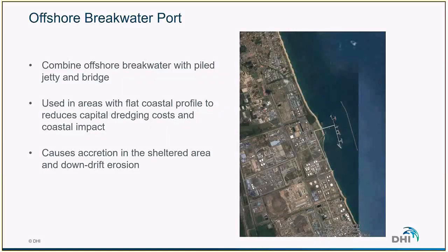However, as we can see on this picture, in this specific case, this very long breakwater has had a significant impact on the coast. So we can see a relatively large accumulation in the shelter of the structure. And we can also see that this has been leading to some sort of erosion south of the structure, because we can see that some groins have been added in order to maintain the sand in its location.